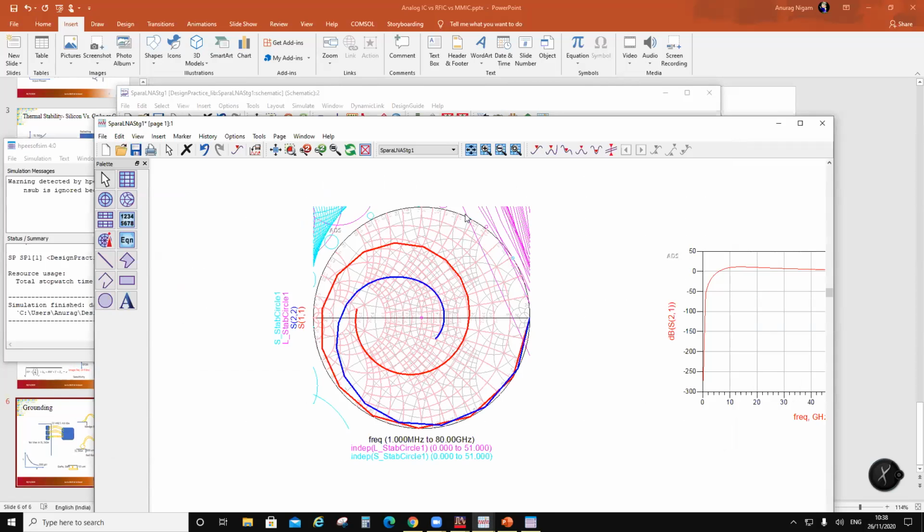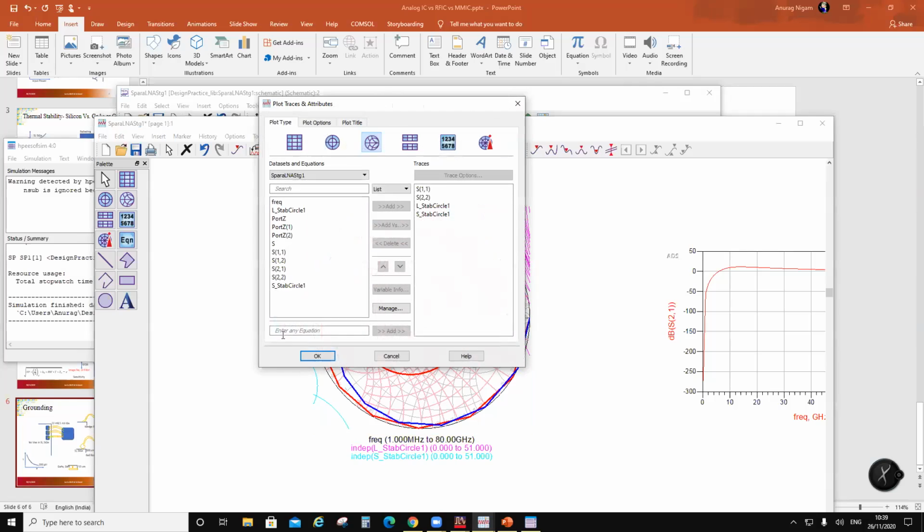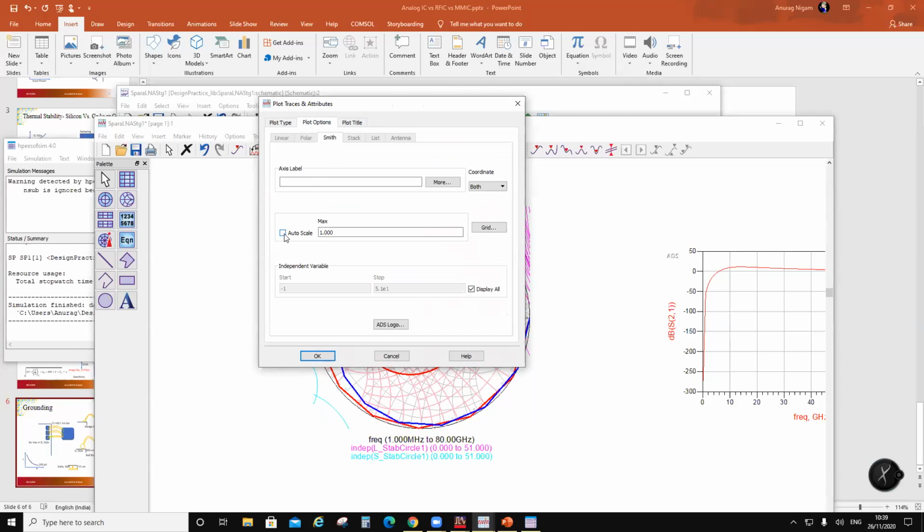Now what you see as a line, don't confuse them with a circle, because what happens with ADS is if there is a circle and the circle is terminated before, then the graphics connects the endpoints. So these lines which you are seeing crossing are not circles, they are not part of circles. The circle was terminated and the graphics couldn't handle that because it was considering a closed loop contour, so it joined the endpoints. If I change the scaling, these lines are going to move.